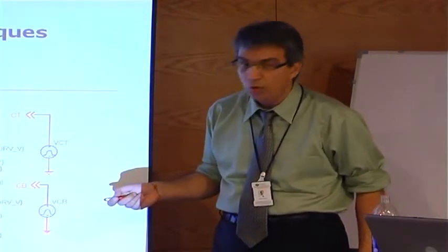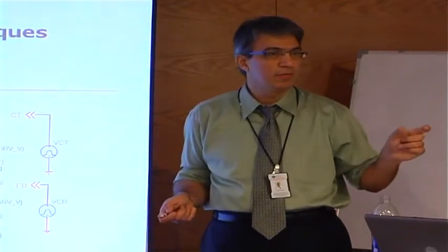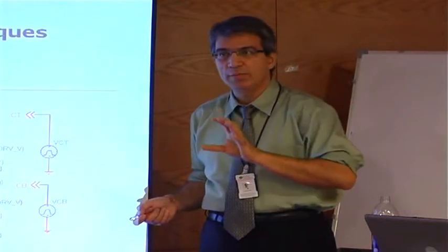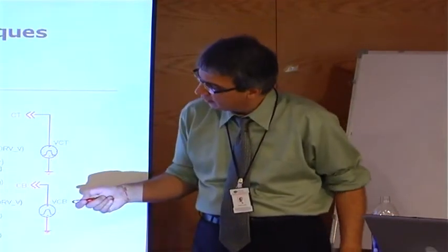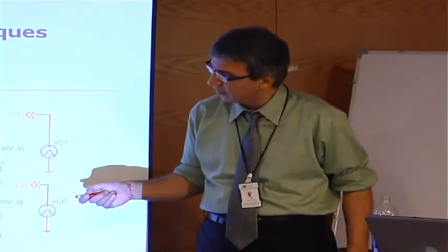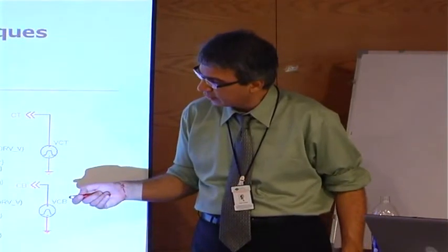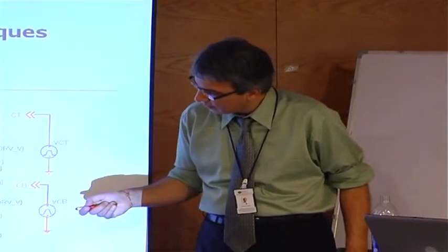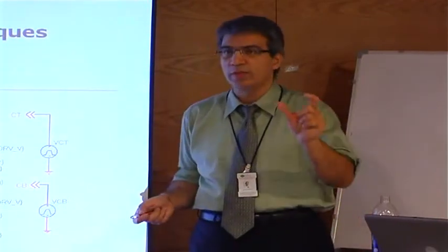The rise time and the fall time is set at 10 microseconds. Probably too much, but it's not too much for back EMF voltage. Actually, sorry, it's the logic. I think it's 10 microseconds, and that's maybe too much. The pulse width, of course, is 120 degrees.